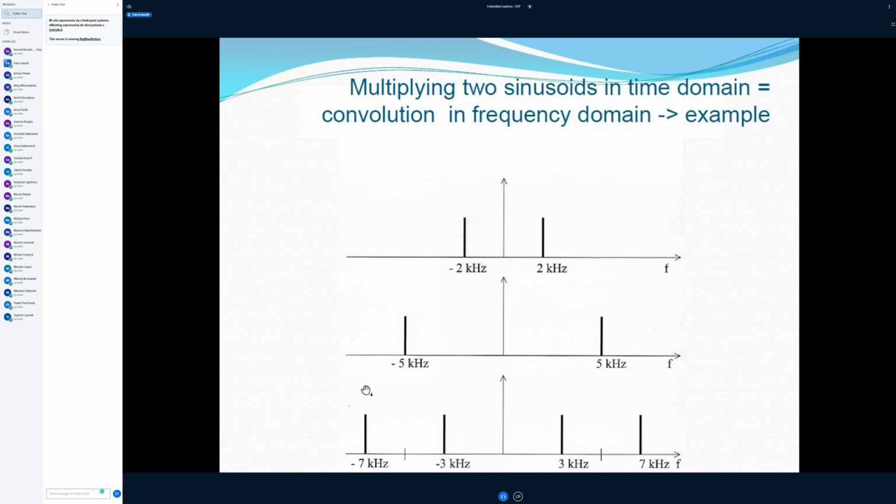So you put this impulse in the place where the zero of this first function was moved. I cannot draw here, but if you take this spectrum and put it here, then the middle is the zero of the axis moved to this place. That's why you have the impulse placed at -7 kilohertz.